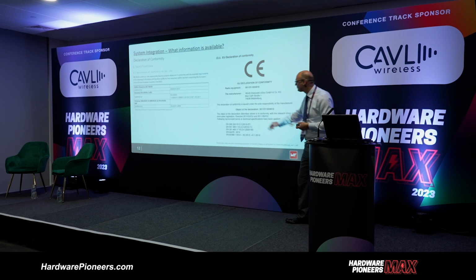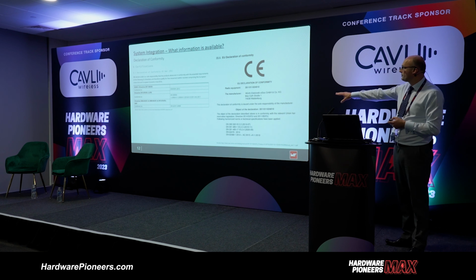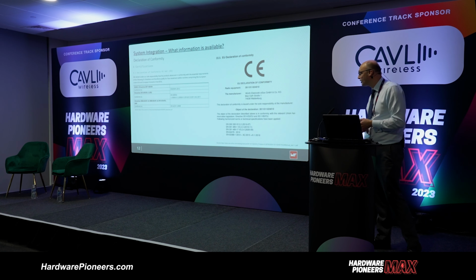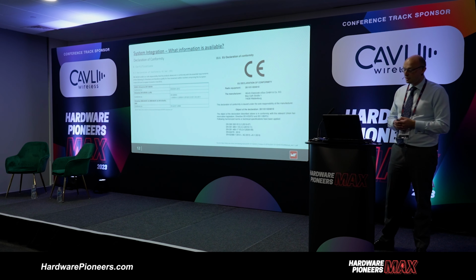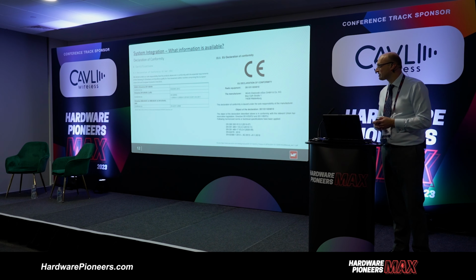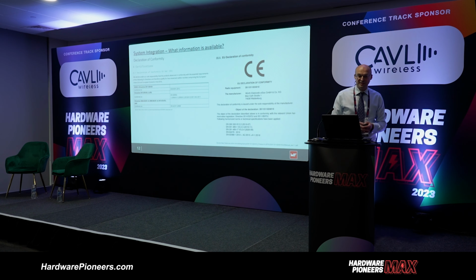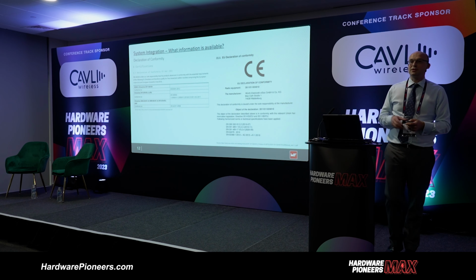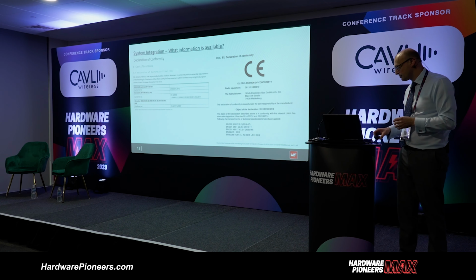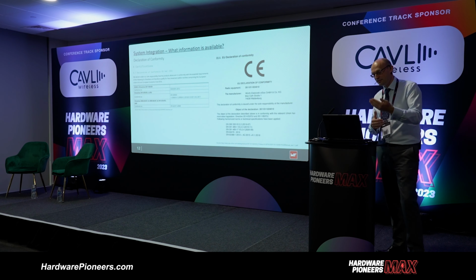With regard to the standards, we've got our actual radio standard, EN 300 328. We've then got the EMC requirements, 301 489, and the various parts, 62479, and then 62368, which has now replaced EN 60950 with regard to low voltage. There is a mismatch between some of those standards, and this is where, once again, when you're looking at integrating a pre-approved module, you need to have a look at that documentation. You can't just take for fact that it's CE marked.